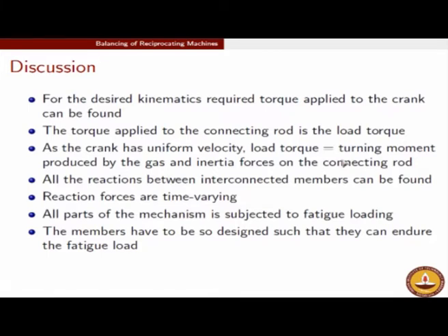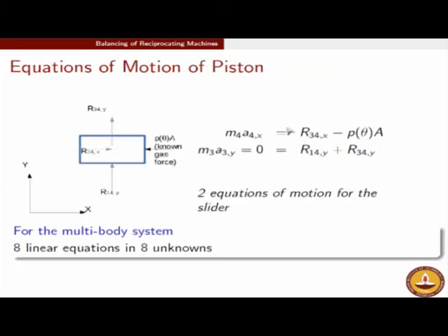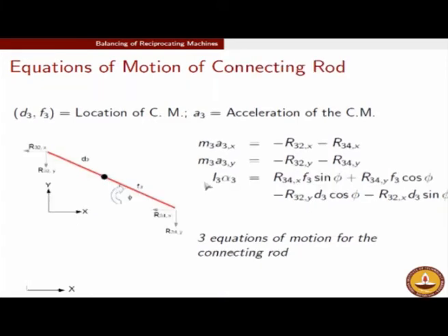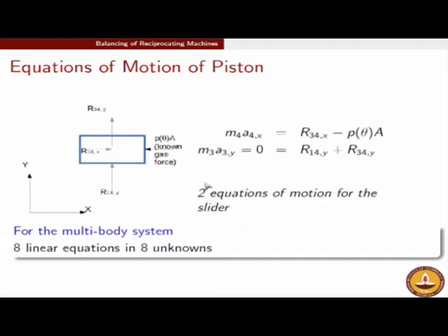So if I look at the free body diagram of the crank, which I will bring up again in a moment, this is the free body diagram of the crank. This blue arrow is the load torque M, which we have found. These two forces taken together will form a turning moment, right? This turning moment and the load moment have to balance such that the crank is rotating at a constant angular speed about this point, and this is what we will try and achieve through our flywheel.